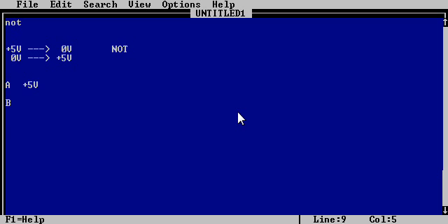So if I put 0 volts at A and 0 volts at B, I want a single output, and it should be 0. Otherwise, if this is 5 volts and this is 0 volts, I want it to stay 0 volts. But if they're both plus 5 volts, I want this output to be 5. The output's usually labeled Q or something. And this operation is called AND.